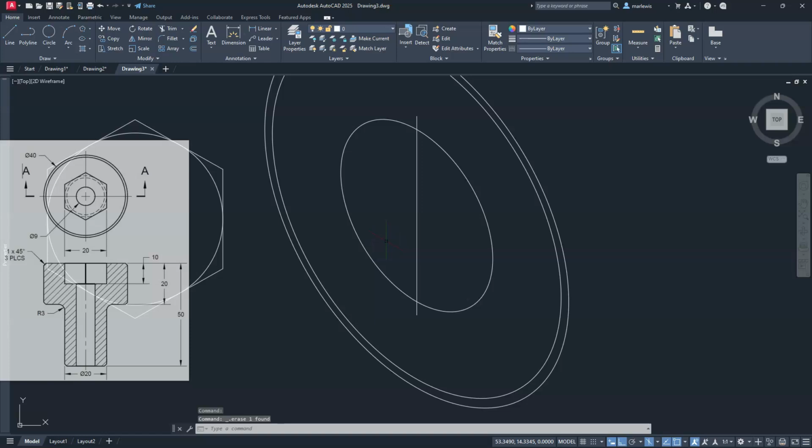All right. So in order to create or figure out where my edge is, I'm just going to start off by drawing a line. My ortho is on, and I'm just going to take a line going straight across this direction, right? Doesn't matter the length right now. I'm going to select this line here. Then I'll go ahead and select this midpoint here, and then I'm just going to place it at that midpoint. Okay, so now what I need to do is go ahead and place this edge. So I'll select it here, grab that grip, and place it at this intersection that's located here.